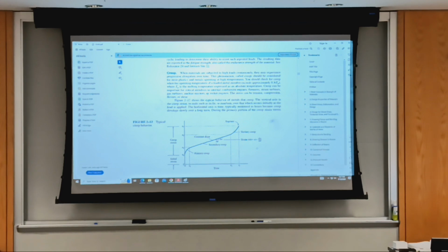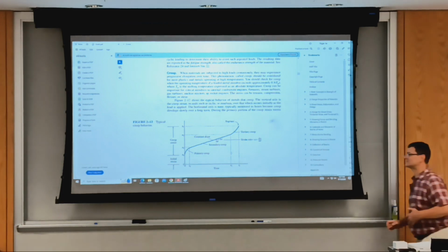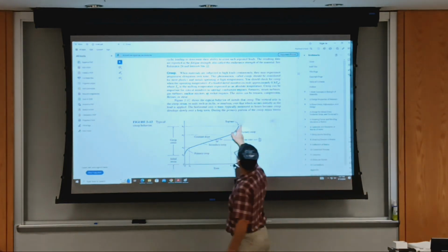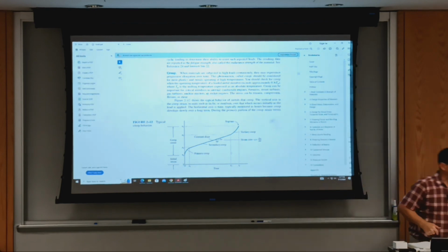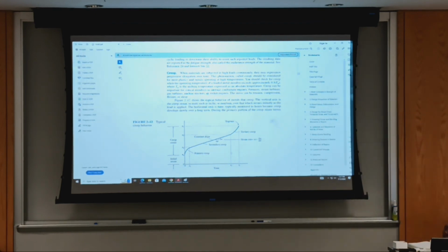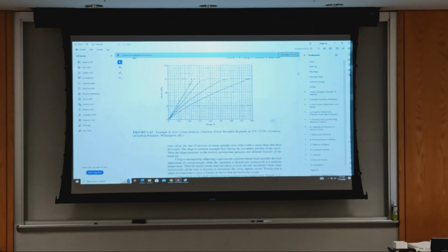Anyway, the company gave a reward to anybody who could find the blade, and a farmer found it 3 months later and returned it for the bounty. They analyzed the type of failure, and there were defects, but this also played a role: the elevated temperature in the gas turbine, and centrifugal force that essentially stretches the blade.